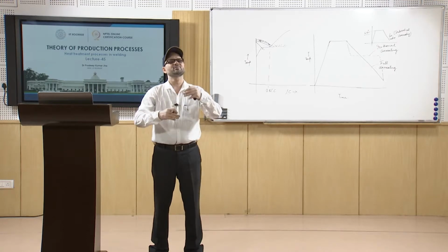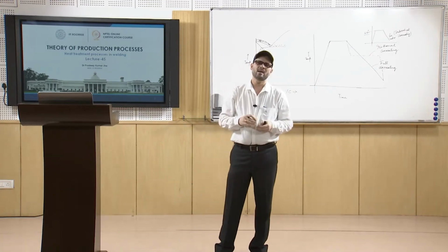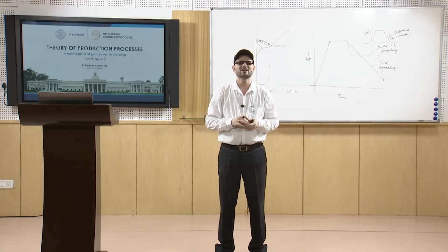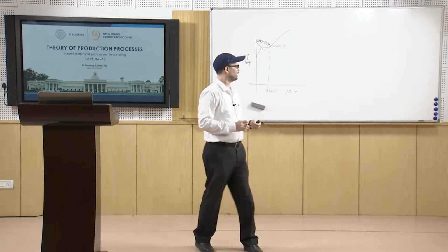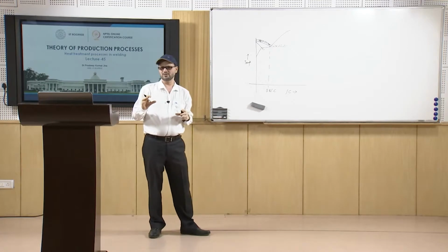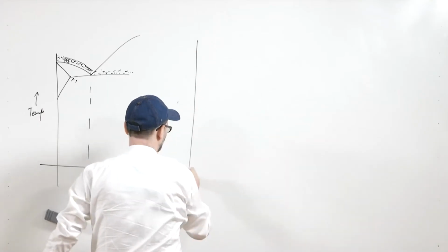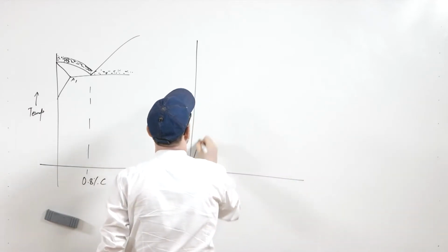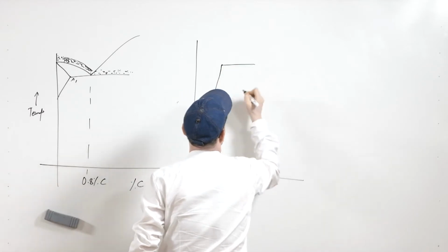The tempering treatment induces certain softness, and it decreases the brittleness which we get in the case of quench hardening. Now, as we discussed, in quench hardening you again go to this temperature and then hold for some time.